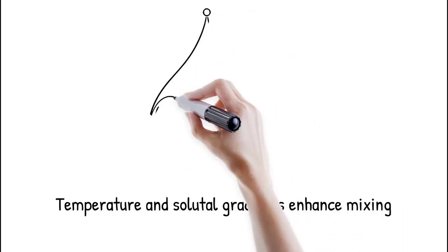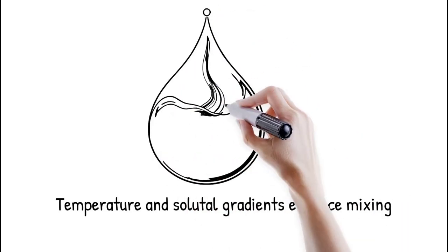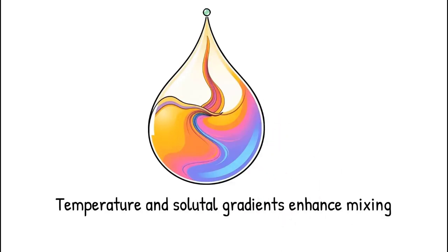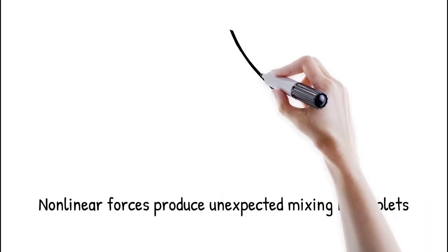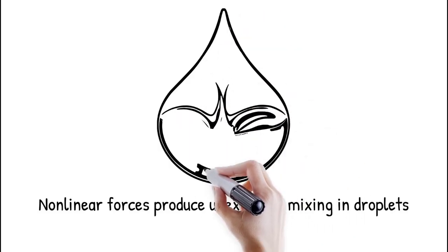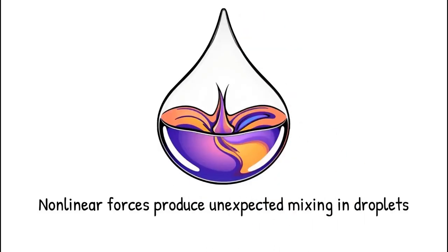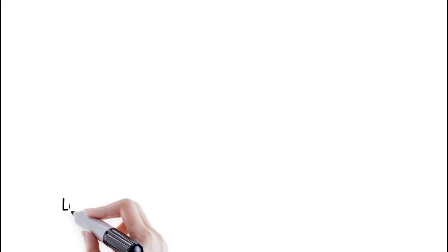Temperature gradients amplify mixing through thermocapillary Marangoni flows. Solutal gradients from differential evaporation reinforce this effect. Together, thermal and concentration fields couple into strong interfacial stresses. These forces are nonlinear, producing unexpected mixing even in symmetric droplets. Localized heating by lasers or substrates further intensifies flow.